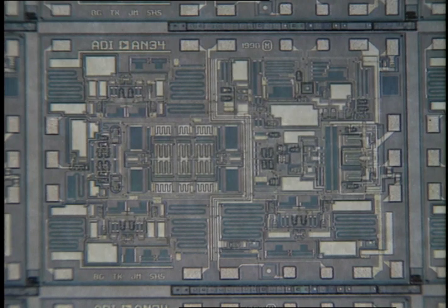In another direction of improvement, this product, the 8734, incorporates laser trimming to eliminate not just the input and output offsets and set up the scale, but also to minimize all harmonic distortion terms to about minus 80 dBs. In this case, by trimming out the VBE errors, which lead to even-order distortion, and ohmic errors, which lead to odd-order distortion. This part's also interesting because it can be used as a very accurate two-quadrant divider with a 1,000 to 1 denominator range and a 200 megahertz gain bandwidth product.